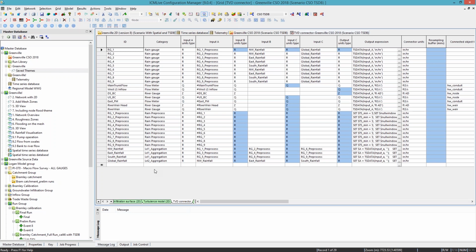If you also think of the way rain data works, often it falls out. You'll have a rain gauge drop out. So here you're able to set up multiple inputs, where if I have multiple rain gauges and one drops out for a particular period of time, the TSDB technology will understand that the data feed has dropped out and it'll pick up an alternative rain gauge.